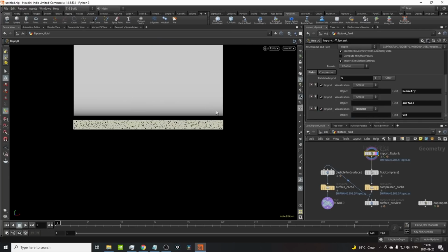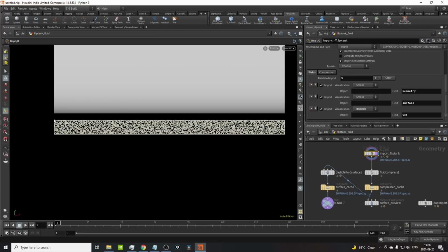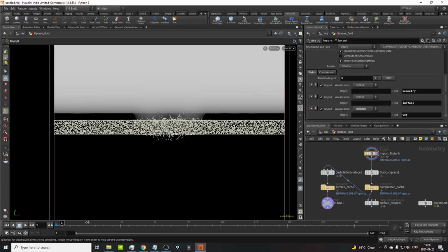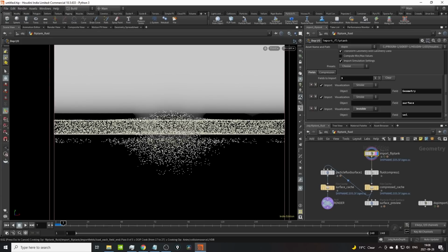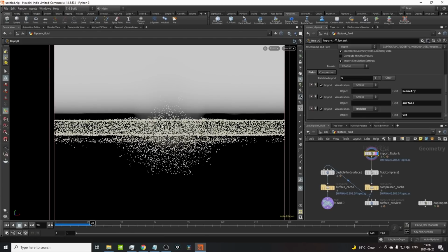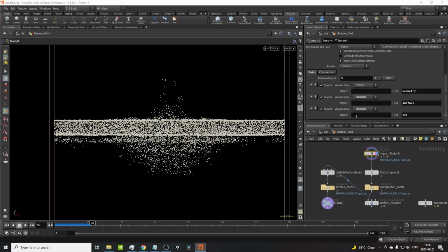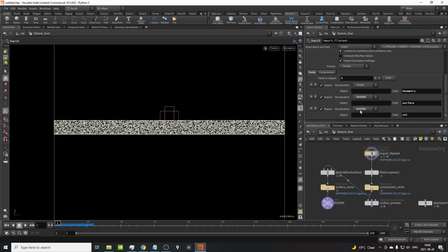this surface layer for FLIP simulations describes by being in positive values what is outside of water, and with negative values what is inside of the water, standard SDF, but 0 is perfectly the surface, right? So wherever the water is, we're getting a 0 right on this edge, okay? So that's the surface layer, very, very useful, very important to have. And let's go over here and set that back to invisible, and the velocity value matches the velocity.